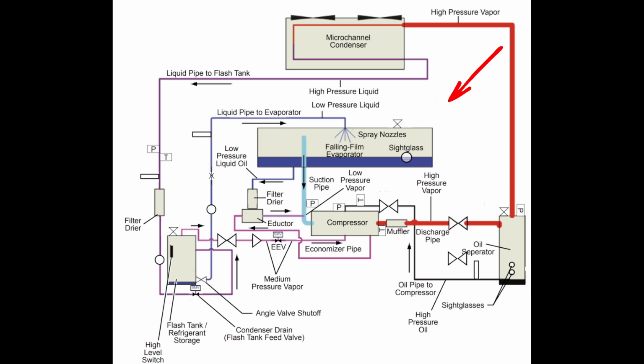Typically, they will either be a brazed plate or a shell and tube DX evaporator, which we don't need an oil recovery system with, if everything is functioning properly. So my point being, this gets confusing as you start getting more advanced into the air-cooled side now, because these eductors are starting to be implemented there because of the types of evaporators we have.